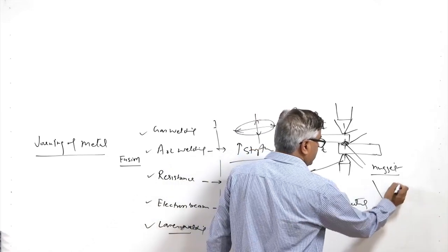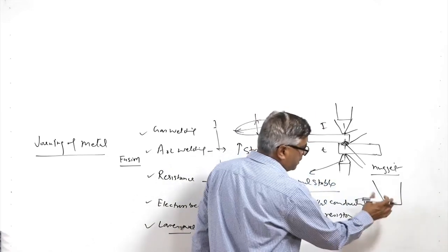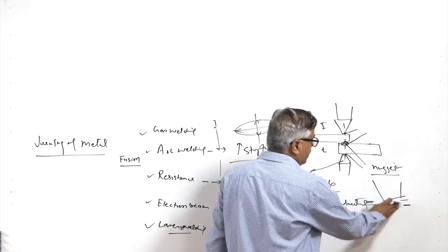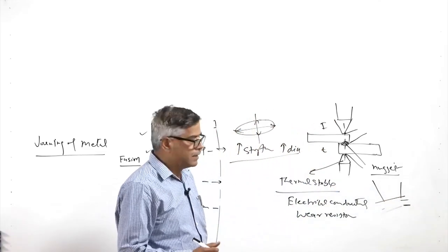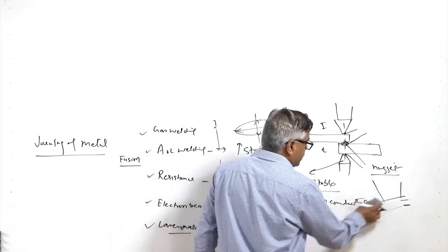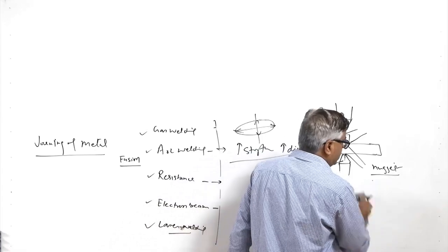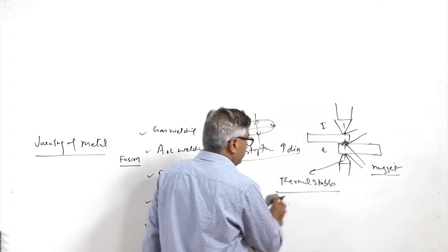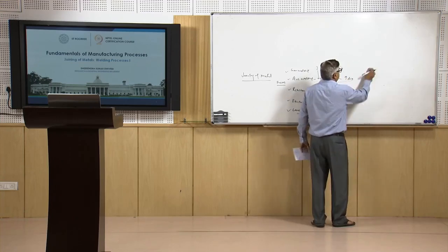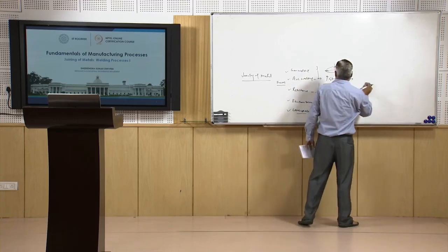It is important that the diameter of the electrode remains constant, because gradual wear will lead to an increase in diameter, which will lead to a reduction in current density, and the reduction in current density will reduce the nugget diameter. So, if the electrodes wear out, they will adversely affect the nugget size, which in turn will affect the joint strength.